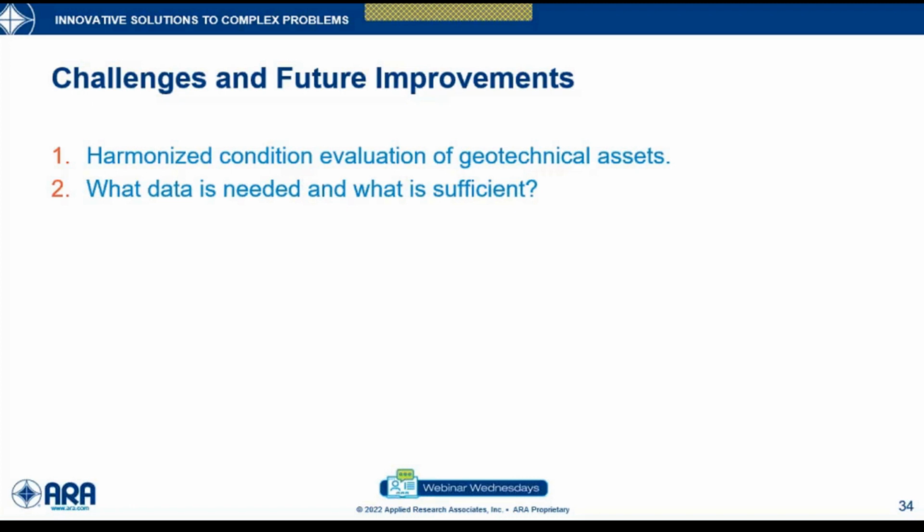And other asset management programs went through that process. For example, pavements. At the early stages, tracking was visual inspection. Then people moved into collecting images. And now there are autonomous algorithms that can extract information and summarize it in terms of how much cracking we have. Do we need all the details and the images? It's good to have a database at some point, but it's not necessarily needed to assess the condition for these pavement sections.